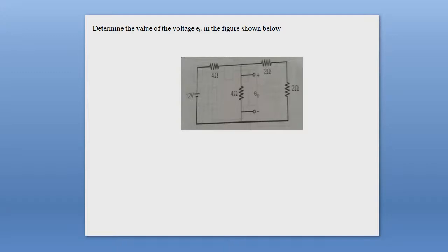You see, when you travel from the positive side to the negative side of a source, then voltage actually increases or decreases? Decreases. Negative sign will appear before the source. So minus 1 minus E minus 10 minus 5 equal to 0 you will get.